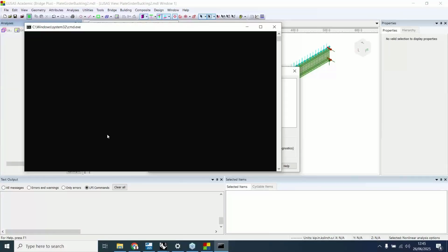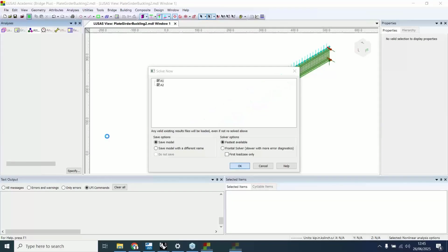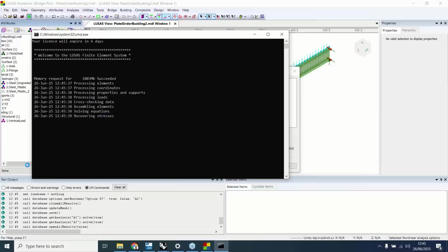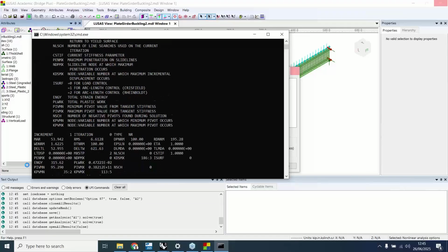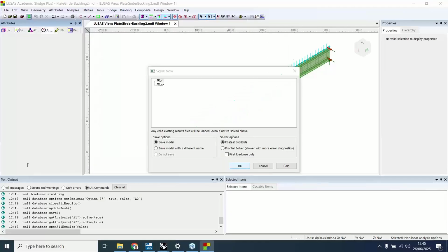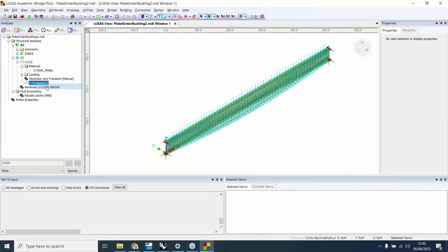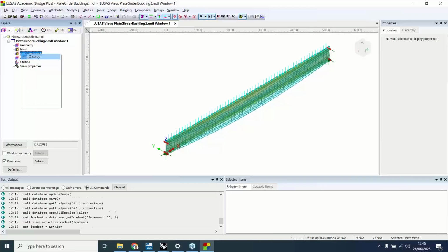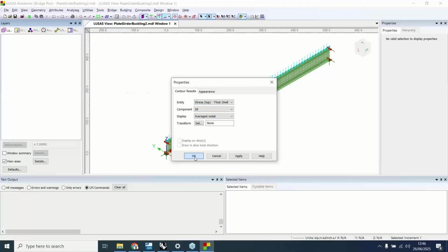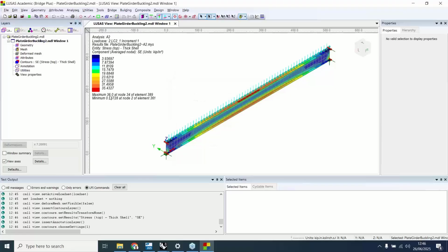This is a very simple model. Of course, nothing's curved. I don't have any initial imperfections. I could add these as a fraction of a buckling mode. But just for you to look at what of the output you can get in LUSAS, you can pretty quickly show the zones of plasticity, where the steel has yielded, and so on. So for example, here you have the nonlinear analysis. If I just go back here and show, not the displacement, but rather the stresses, this is the von Mises stress SE. I can see that, yeah, this is limited to 36 KSI, as I've specified.